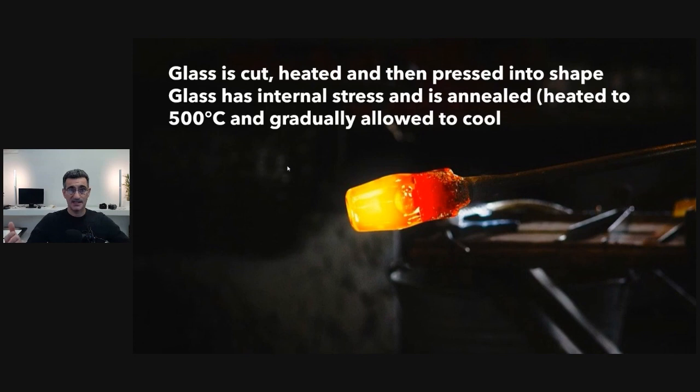If you were to just take hot glass and pour it out on a table and let it harden, there's a lot of internal stress inside the glass, and sometimes as it cools, it just shatters on its own. So in order to avoid that, you anneal the glass, and you get up to about 500 C, and then you gradually allow it to cool.